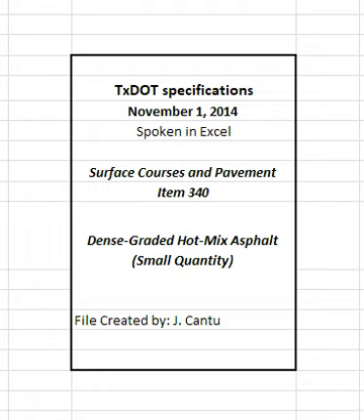4.9.2 Miscellaneous areas. Miscellaneous areas include areas that typically involve significant handwork or discontinuous paving operations, such as temporary detours, driveways, mailbox turnouts, crossovers, gores, spot level-up areas, and other similar areas. Miscellaneous areas also include level-ups and thin overlays when the layer thickness specified on the plans is less than the minimum untrimmed core height eligible for testing shown in Table 12.